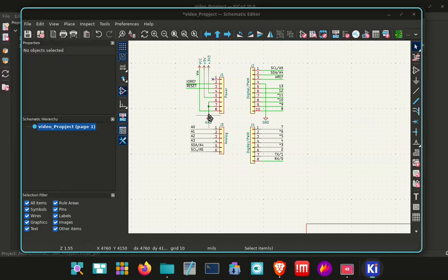For an LED, which is what, 1.8 volts maximum forward and 15 milliamps, we are looking at having, and the Uno kicks out 5 volts, so it's 3.2 volts difference. We want a 220 ohm resistor.